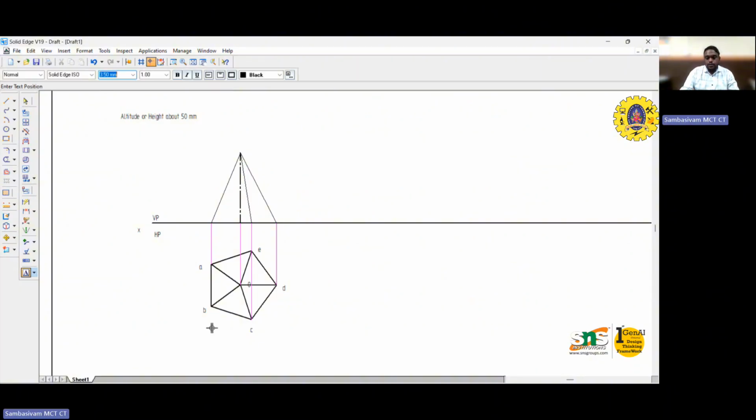So the next part is marking. When you look from this portion, over the imaginary position, the visible side is B and the non-visible side is C. So we can mark it as B dash, with A dash in brackets. Similarly, this portion will be represented as D dash. This portion will be represented as O dash.